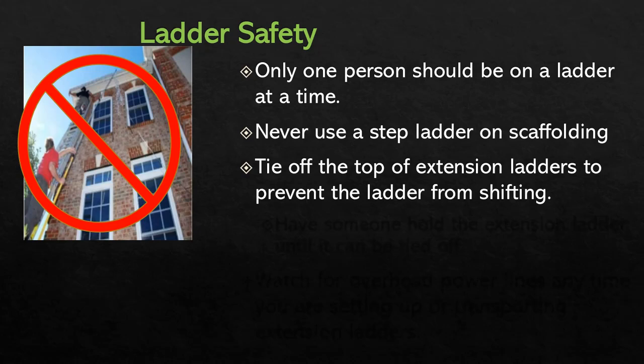If you don't want a ladder to shift while you're up on it, consider tying off the top of the extension ladders to some sturdy object on the roof or along the wall that the ladder is on.